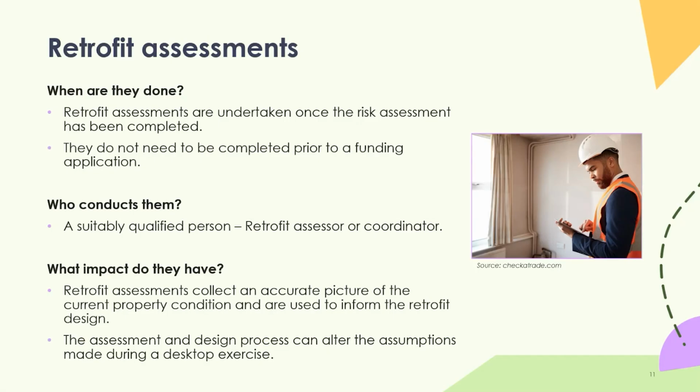So just moving on to retrofit assessment. Retrofit assessments are undertaken by a qualified retrofit assessor or a coordinator, depending on the complexity of the assessment, and that is determined by things like heritage and non-standard building types. So where you might have higher levels of risk and maybe specialist knowledge requirements for the assessment of the building.